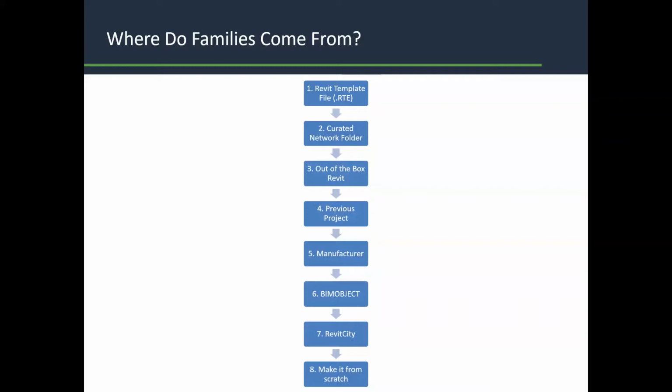And when you use manufacturer's content, it's almost always modeled to LOD 400. And not many projects require LOD 400 components. That's highly detailed. So when you put this highly detailed item into your relatively poorly detailed project, it does not have the effect of making your project look better. It has the effect of making your project look unfinished. Manufacturers' content can be bloated with thousands of texture files or unnecessarily dense geometry, and this will bloat your project.